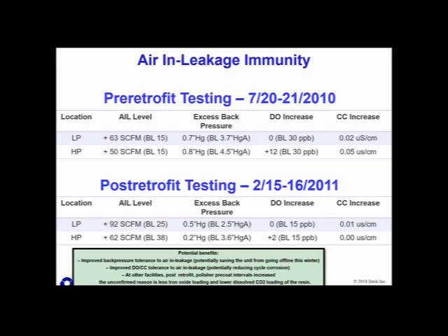I've walked you through fundamentals of monitoring the condenser, troubleshooting the instruments that you have in your plant. I've talked about how to use the re-evac tool, how to monitor cooling water flow rate, and if you have a condenser that has been just a headache from the beginning, historically having low cleanliness factors, I've walked you through a process that you can use to find out if there's a project worth doing an upgrade on the condenser.